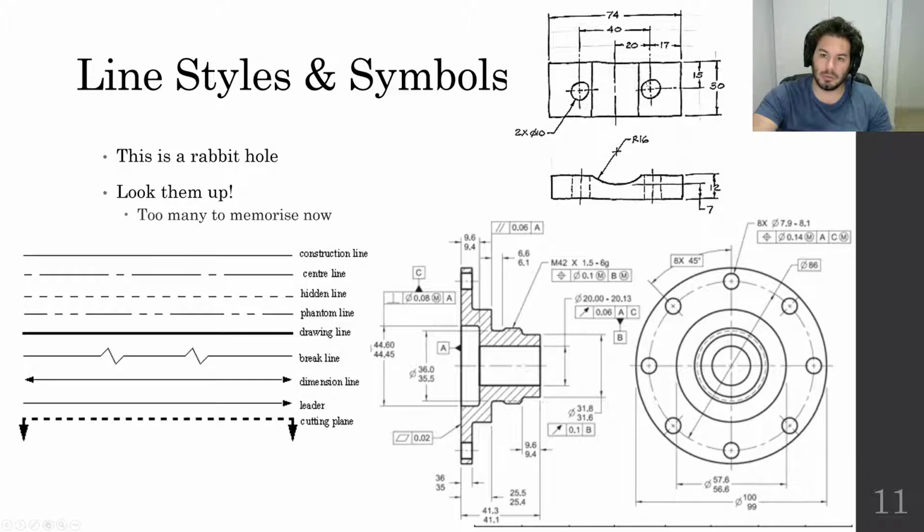Whenever you put a hole in, the convention is you put two intersecting center lines in the middle of the hole. If ever you do this, this implies to me this object is round, and this is where the center of the circle is. They're important because if you just put a hole in something, its center has no geometry. There's not actually anything in space at the center of this big 32 diameter or radius 16 hole. So if you wanted to dimension to the center of it, you need something to tie that dimension to. Center lines are great for that. So you can see that's a distance to a center line. Okay, so there's center lines.